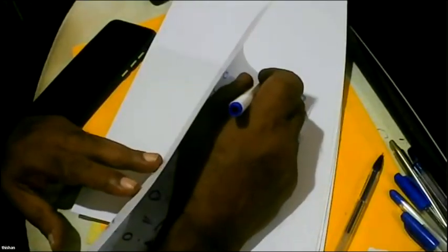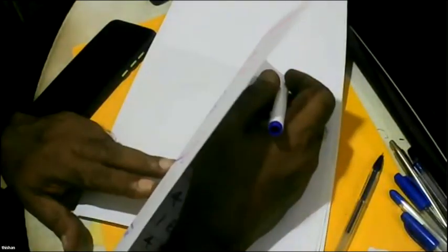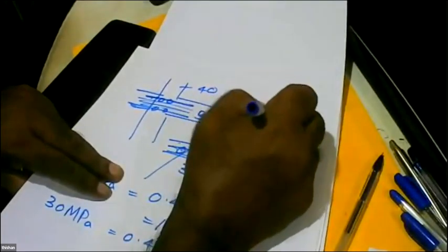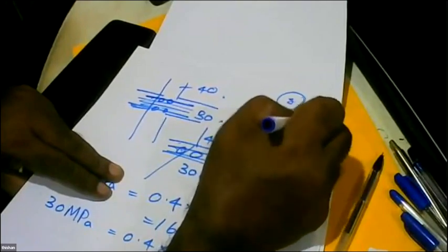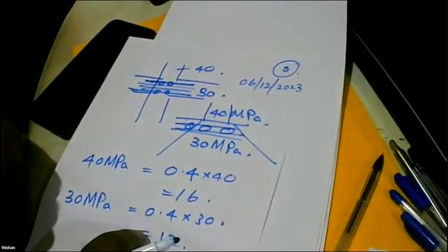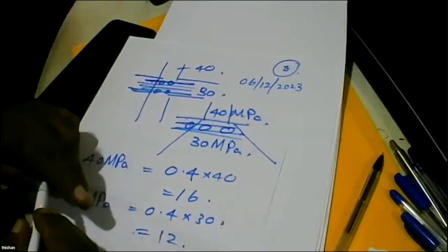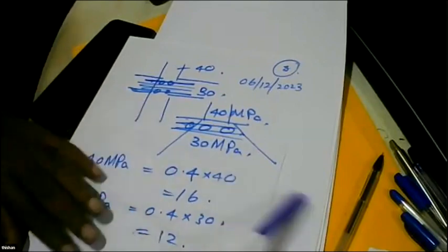impurities are low. So you have to get the fly ash which has passed the tests. If you ask a cement manufacturer, they buy only the fly ash that passes the carbon test. If there is too much carbon, then it's an impurity. So you have to get the specification for class F fly ash and check whether the product that you buy satisfies that. But the moment many construction companies are buying fly ash, it will become readily available, high quality fly ash.